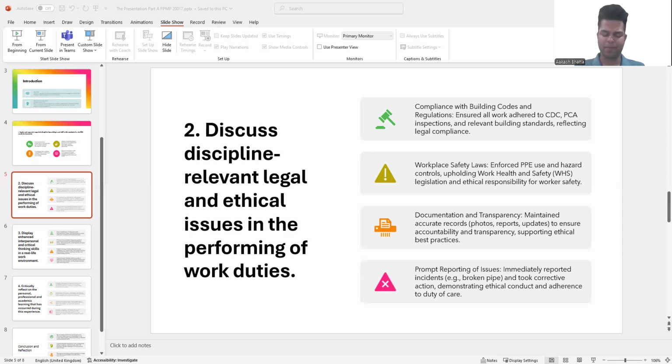And for the stormwater plan for plumbing works, we need the PCA approval. Even before pouring concrete, while laying the rebars, we try to make sure the laid rebars are in order with the structural drawing.